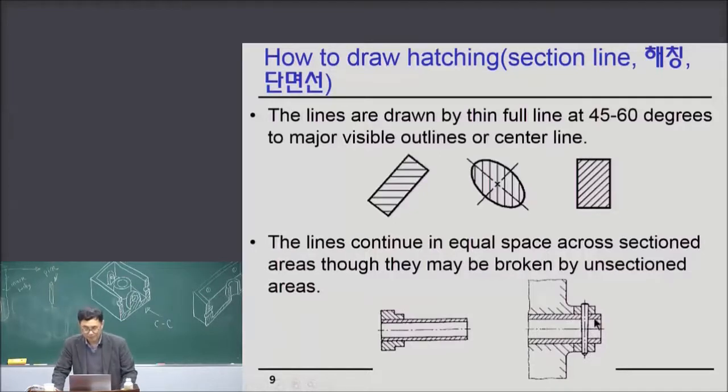Of course, since the sectional area of the pin is very small, because of that area, the pipe and ring are combined together. So since the pin has a very small area, if the external torque is large, then maybe the pin can break. The key is relatively strong because the sectional area is large.